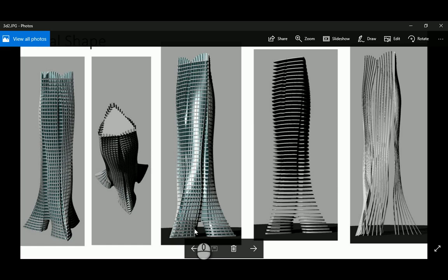If you remember the last video of the Snowflake Tower series, it's 11 videos, video number 11 specifically, we made the surface, and then we made the solid, and the solid gives us those horizontal elements in the slab later on, and the vertical one, or the surface one, actually gives us this skin, with the crown on the head. And those horizontal elements we made by exporting the geometry to Revit as a conceptual mass, and then we slice it, rather than the vertical elements, and the division we made based on the surface itself.